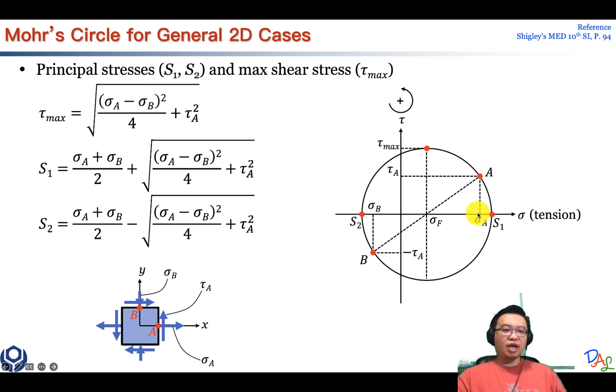At the beginning, when you draw the Mohr circle, you have this A point and then B point, and because there is normal stress sigma B, it's not right on the vertical axis. It's somewhere in the third quadrant. Then your Mohr circle looks like this. So it will vary your calculation a little bit, but no big difference.